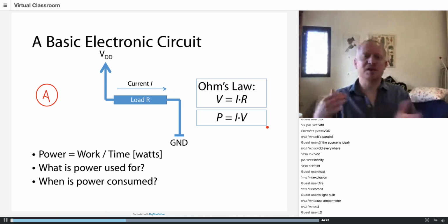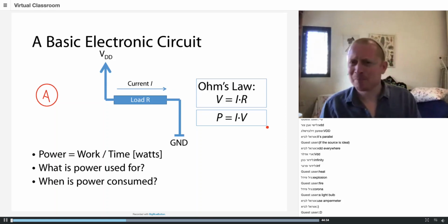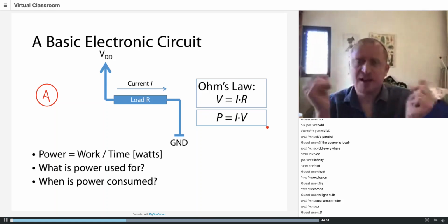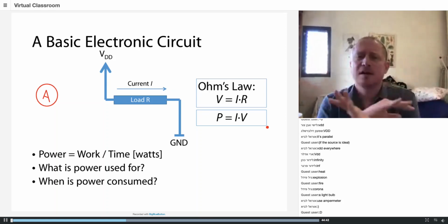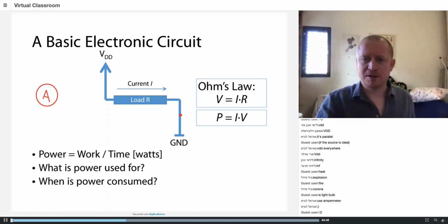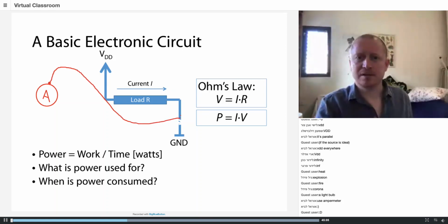And the ampermeter is measuring the current which is going through it. How does this help me to measure the power consumption of the device? Well, the ampermeter, by design, has a very, very small resistance, nearly 0. So what I'm going to do is take my circuit and cut the cable between the VCC and the ground. And you'll see some pictures later today. And I'm going to connect my ampermeter in series to the circuit.